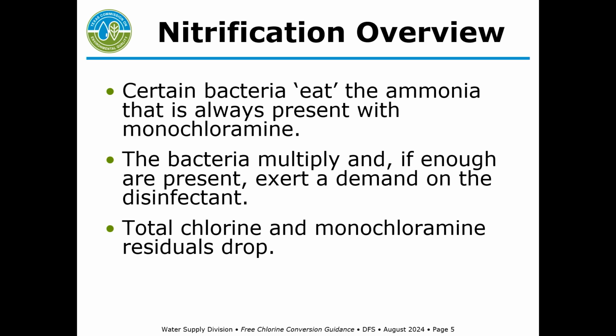All right, so what is nitrification? I'm not going to go into a lot of detail, just an overview. There were other presentations, like by Alicia Deal and Andy Waite, that talked about it, but the basics are you've got bacteria that use ammonia as an energy source, and there's always going to be ammonia if you have monochloramine in your distribution system. These bacteria can then grow and multiply, and if enough are present, they can exert a demand on your monochloramine and cause your residual to go down.